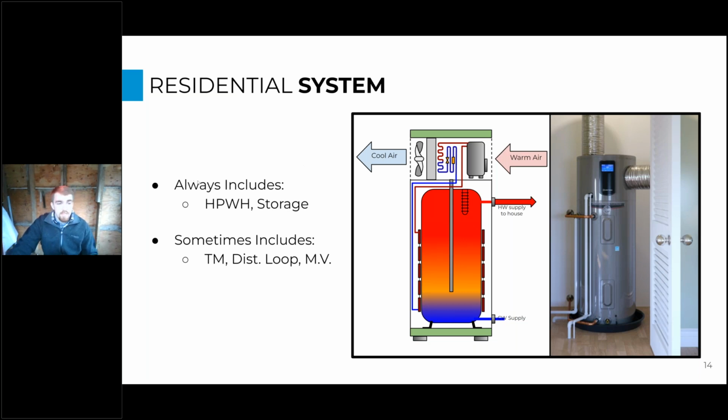And so this system always includes a heat pump water heater and a storage tank, right? Heat pumps do not operate well as instantaneous heaters, so we do want to pair them with storage so they have the nice long run times that they need to be satisfied. And then sometimes they might include a temperature maintenance system, a distribution loop, and a mixing valve, right? So that's if you don't have a really big hot water load, but you still have a big plumbing distribution system you need to send hot water out through,